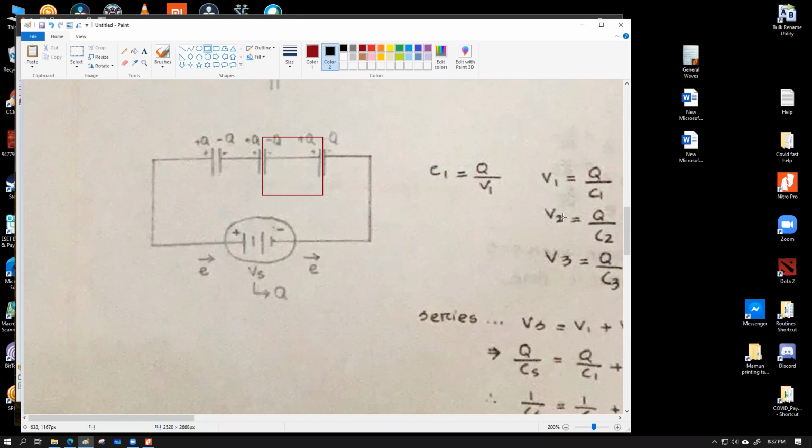We are considering them to be ideal capacitors capable of handling any amount of voltage. So there is no electron leaking across the plates of a single capacitor. The electrons can only move through the connecting wires of the circuit. How is the charge passing? Charges are not passing. Charges are being pushed out because of induction. Yeah, I think I got it. Beautiful. In that case, please lower your hand.